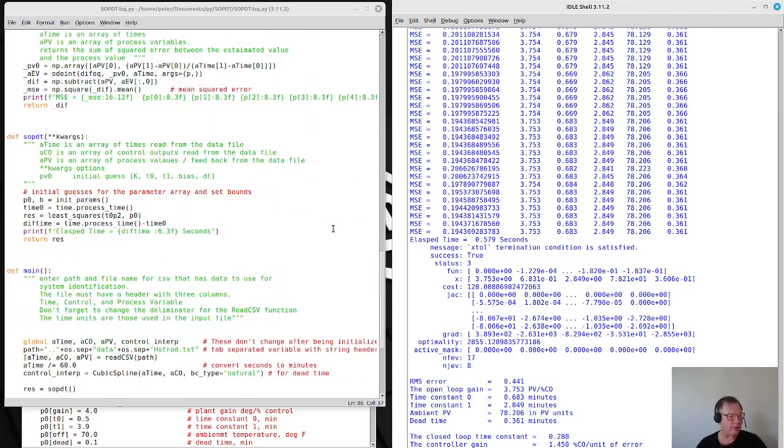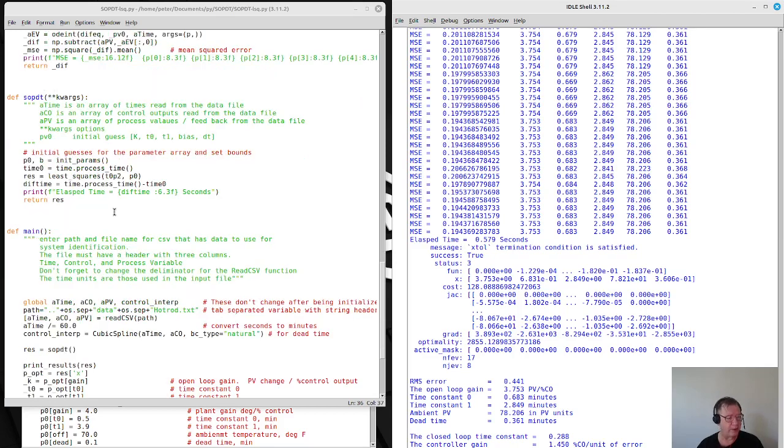This is my second order plus dead time routine, and I'm planning to have a first order plus dead time, but usually a system only has a second order plus dead time unless you want to ignore one of the time constants, which I don't want to do.